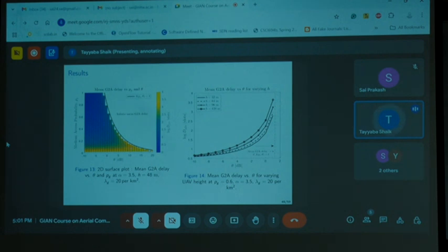All this yellow shaded region corresponds to the higher mean delay. Previously, when you were at p equal to 1, you had a threshold up to some minus 2 dB. But with decreasing p, suppose you are at 0.2, you are allowed to transmit up to 10 dB, but with an increased mean delay, which is again a trade-off.